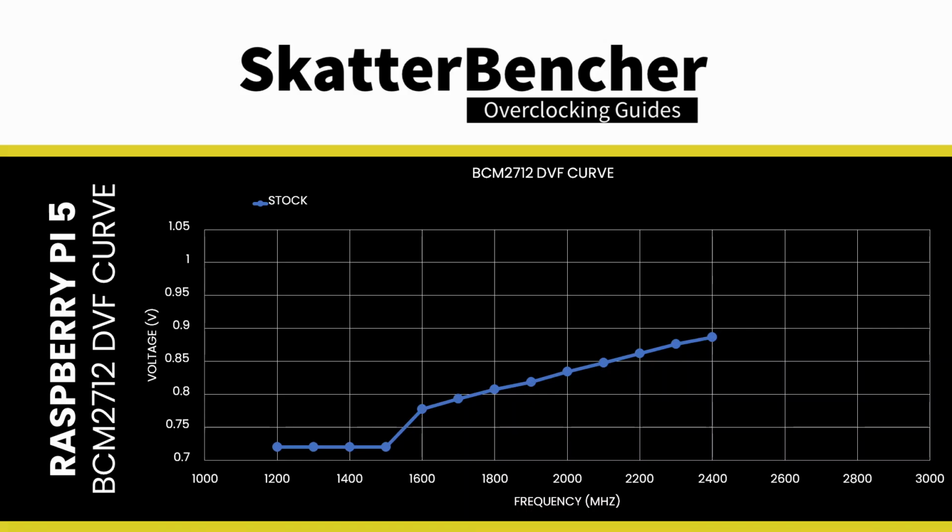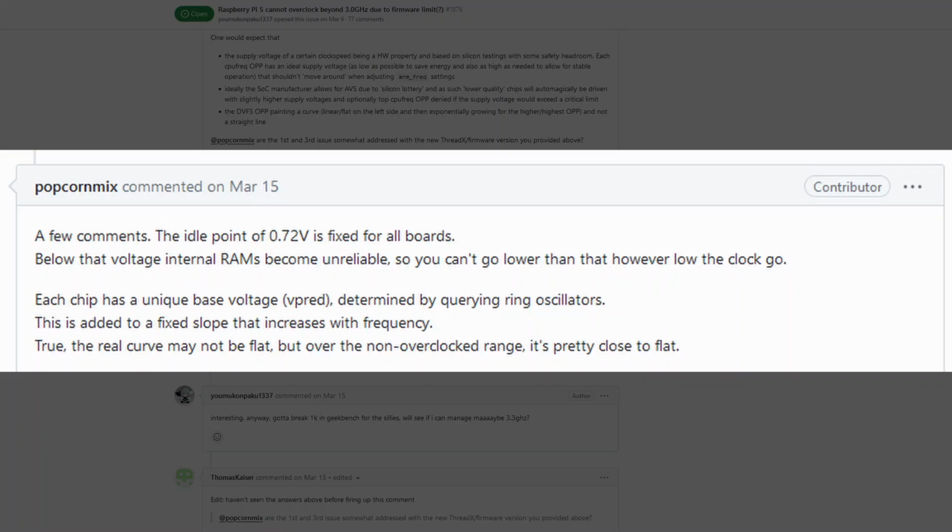Using our telemetry tool, we can map the ARM core's voltage frequency curve. We find that the minimum voltage is 720 mV for 1.5 GHz and below, then increases gradually to almost 887 mV at 2400 MHz. The 720 mV is a firmware-defined lower limit of the SoC voltage. Below 720 mV, the SRAM cache becomes unstable. This is a very common challenge with silicon chips.